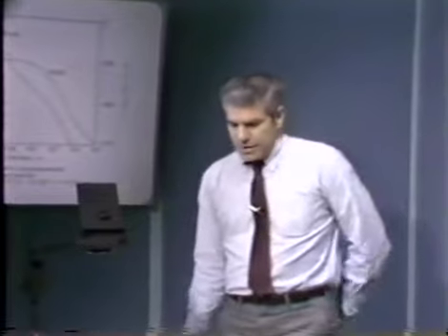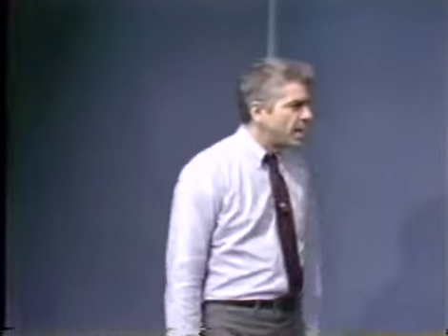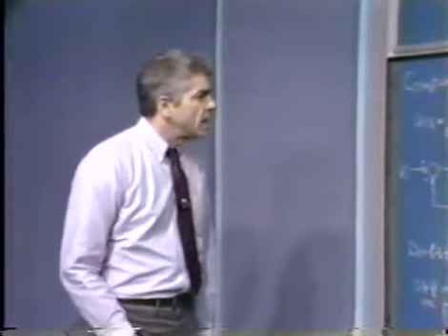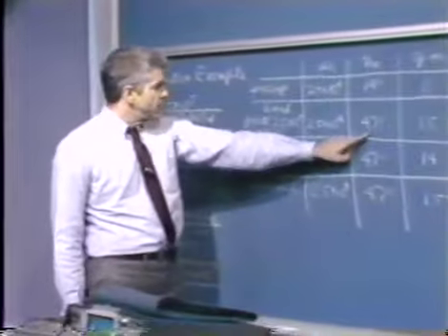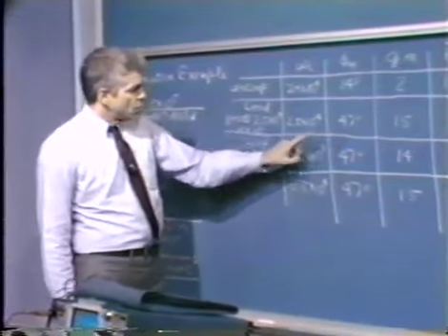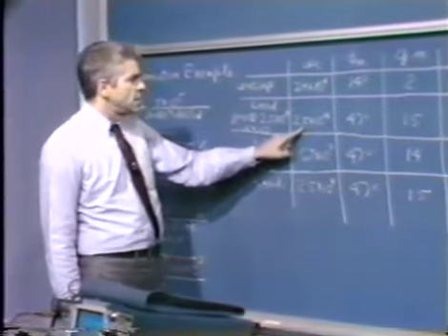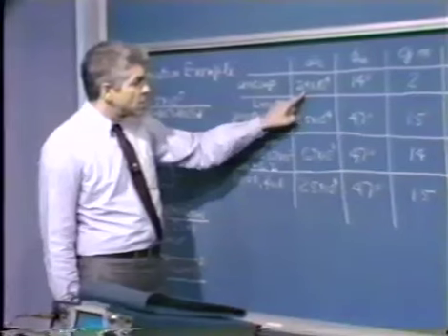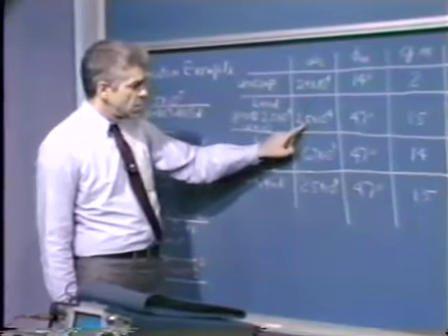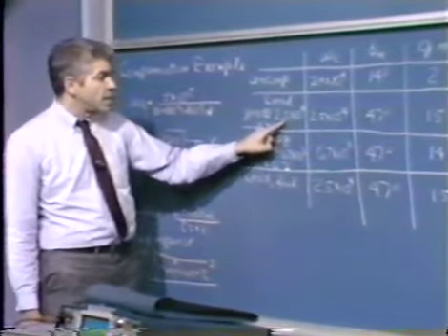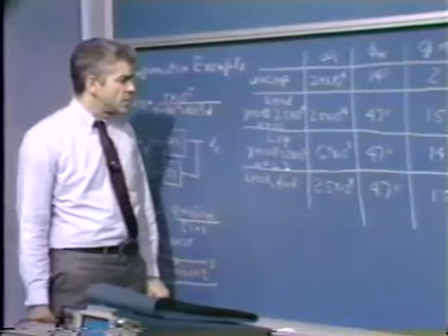When we do that, we find out that our maximum positive phase shift combines with the phase shift associated with the amplifier itself, with the original A of S, and we find that we're able to get a phase margin of about 47 degrees. Crossover frequency with that combination is about 2.5 times 10 to the 4th radians per second. We increase crossover frequency just a bit by adding the zero close to crossover. In fact, the zero location in our lead network comes out just about at the compensated crossover frequency of the system. We can look at that Bode plot.